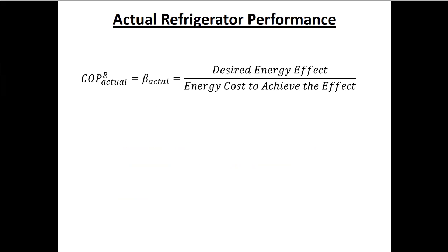So again, here we don't have an efficiency. Refrigerators look like heat pumps in that we talk about something called a coefficient of performance. This is related to, but not exactly equal to, something called a SEER rating, which is what you might see if you're trying to buy something like a central air unit. Now the energy benefit here is Q dot out from the cold place.